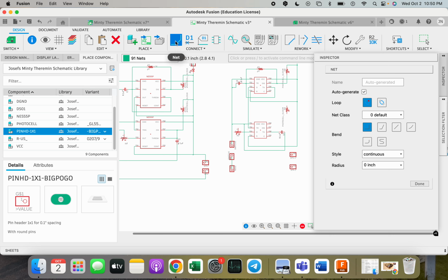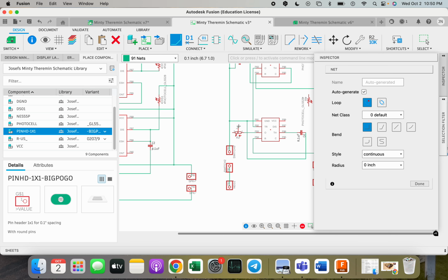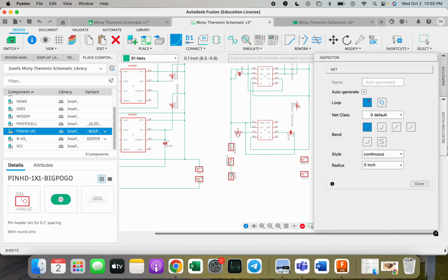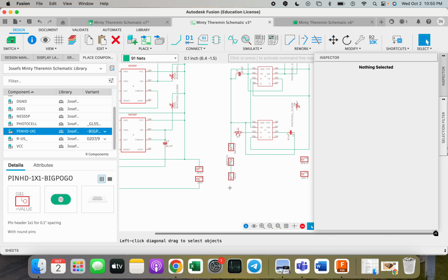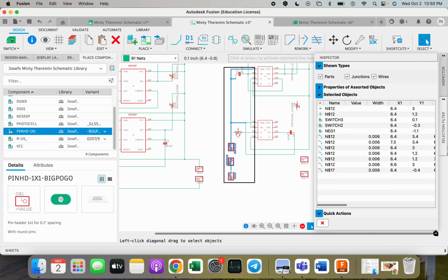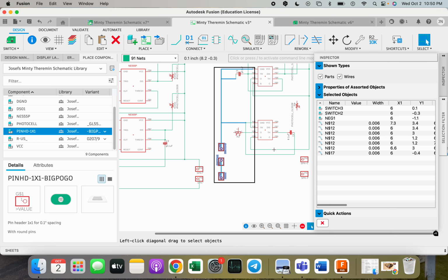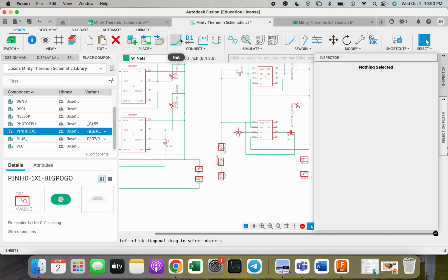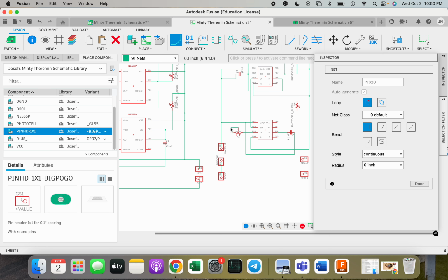and this is where not every schematic is going to look the same. I have a choice of either taking these lines and moving them outwards, or I can come off of pin 2 and cross over. Whenever we're working with schematics, we'd like to avoid crossing over lines as much as possible. So I'm going to escape out of my net command, select all of these lines here, and move them outwards to give myself some more space. Now I can go back into my net command, grab designation 2, and come down onto speaker negative.